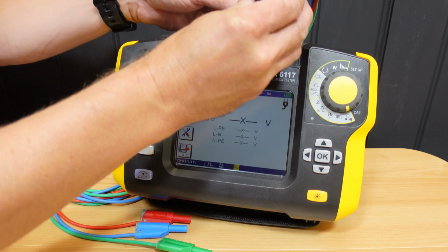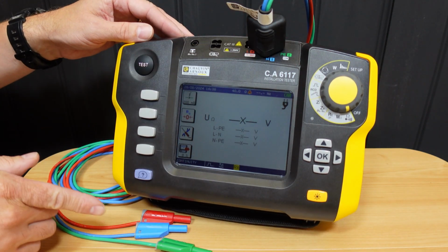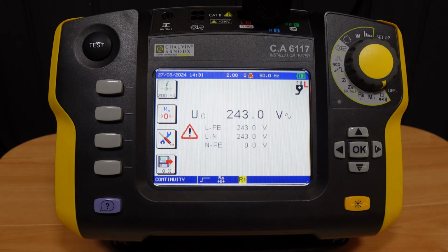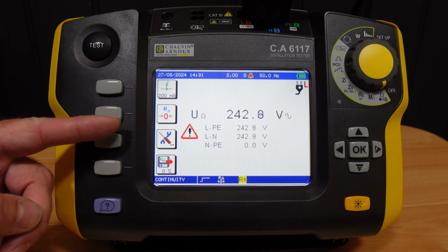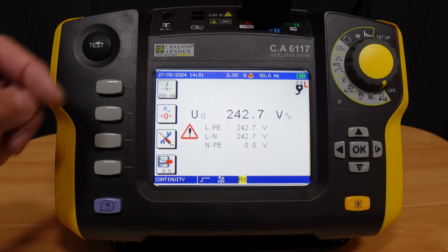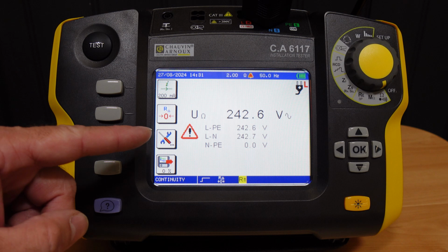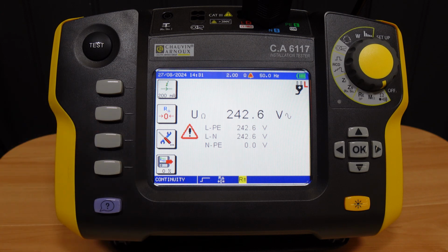Resistance is a two-lead test between the red port, labelled with the ohm symbol, and the green port, labelled as COM. When the three-lead set is used, the blue wire is superfluous and must be left disconnected to ensure accuracy of results. Resistance and continuity are accessed as the first function on the dial selector, and these are, of course, dead tests. So with that function selected, any AC or DC voltage and AC frequency, if present on any connected test leads, will show on screen. A caution triangle warns the operator that dead test cannot proceed and that any voltage source present should first be removed.